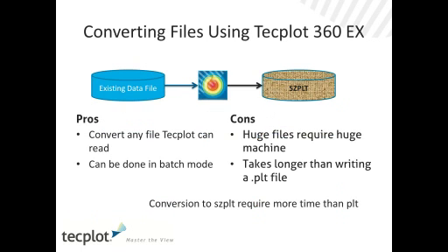So converting files using Tecplot 360EX, you can convert any data file that Tecplot can currently read. And although this may take longer, you can also set it up to do it in batch mode overnight or something like that in the case of really huge files. So at least hopefully you won't have to sit there watching it happen. But huge files do require huge machines, so you won't be able to do this conversion on your laptop, and it does take a bit longer to write these out than writing a corresponding legacy Tecplot data file.